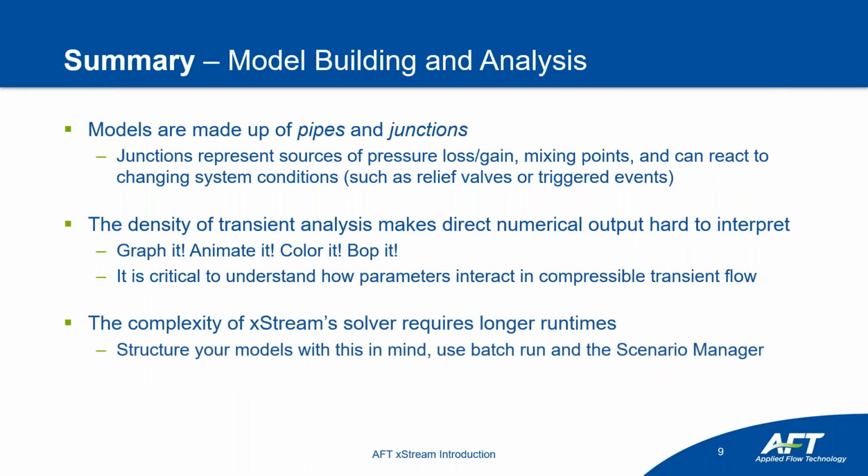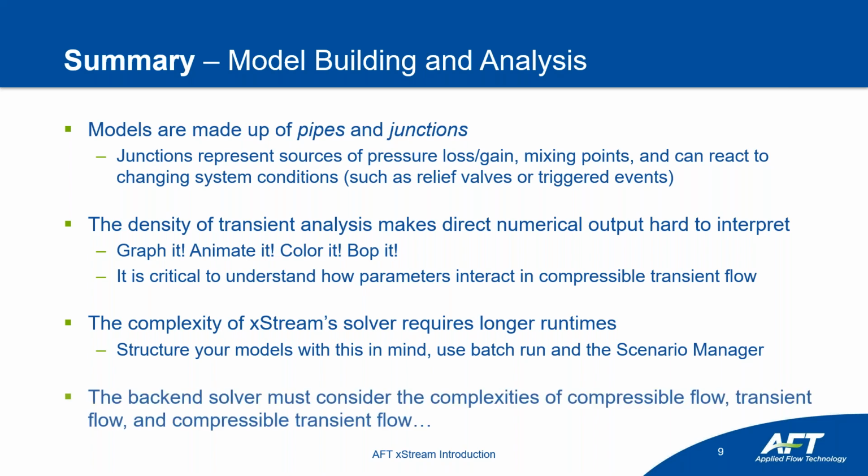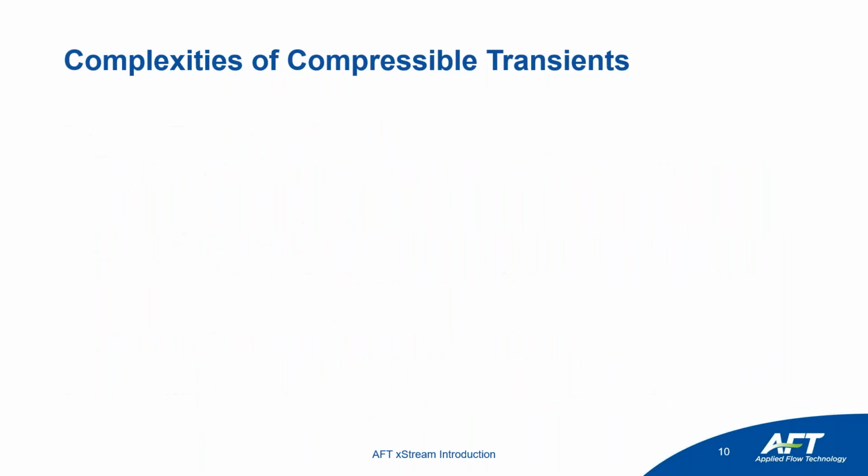So as we saw, the complexity of xStream Solver requires longer runtimes. It's a bit harder to do the quick iterations you might be more comfortable with in Fathom, Arrow, or Impulse. So be sure to structure your models with this in mind, setting up all your design cases, running them in a batch, and leaning into the scenario manager. Then finally, the backend solver must consider the complexities of compressible flow, transient flow, and compressible transient flow, which will be the next segment of our presentation.